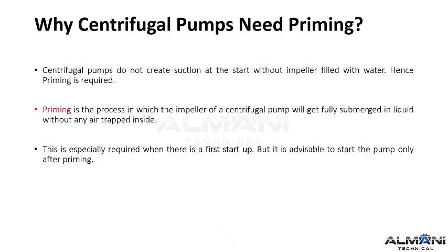This is a critical point. Centrifugal pumps must be primed before starting. Unlike positive displacement pumps, they cannot create suction if the impeller is spinning in air. Priming is simply the process of completely filling the pump casing and impeller with liquid, pushing all the air out. This is absolutely essential for a first startup, and it's a best practice to prime the pump before every single operation to ensure it works correctly and doesn't get damaged.